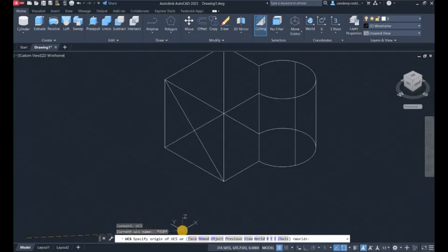What the face option does is, if you select that and click on whichever face, that face becomes the XY plane. And then you have named object, previous. You can go through your notes and explore these other options for changing your UCS. By default it's the world UCS, where the XY plane, the XZ plane and the YZ plane are restricted.